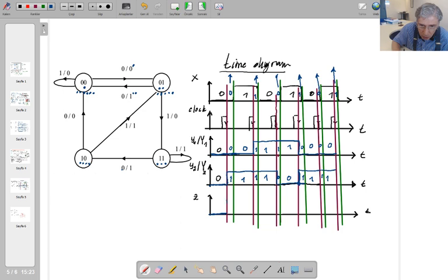I draw in this critical time interval, my output is 1. So what happened in this time interval, this green one and this red one? My present state is 0, 1, that is this one, and my input is 1. In that state, my input is 1, that's the one. So my output is going to be this one. So this one I'm going to observe, third one. In here, it's going to be 0.